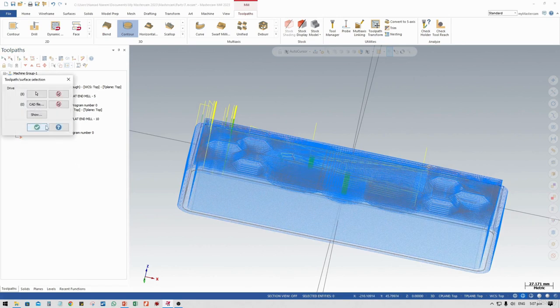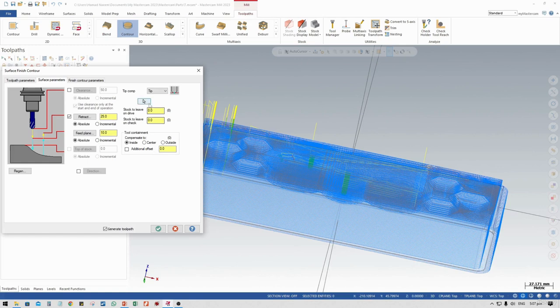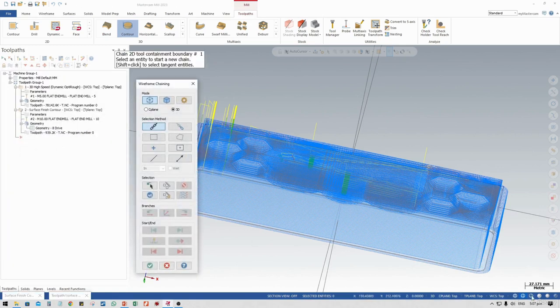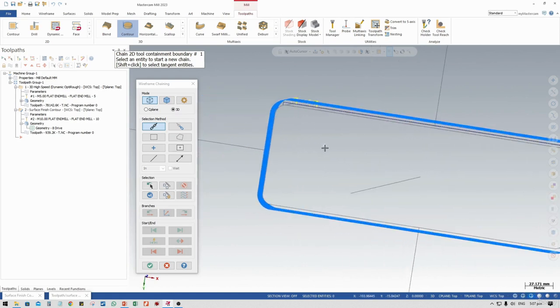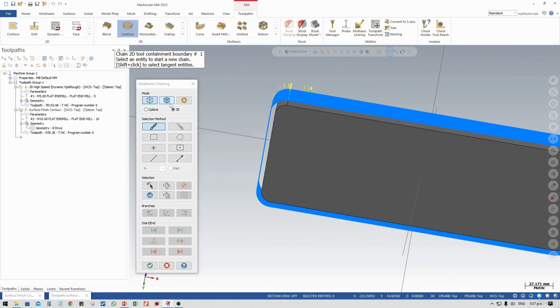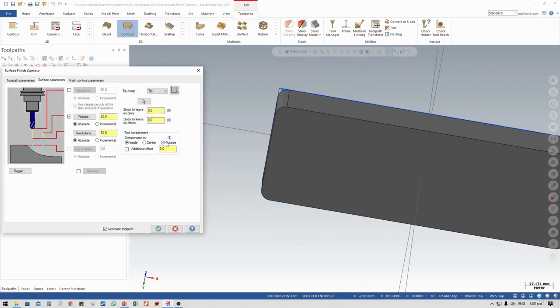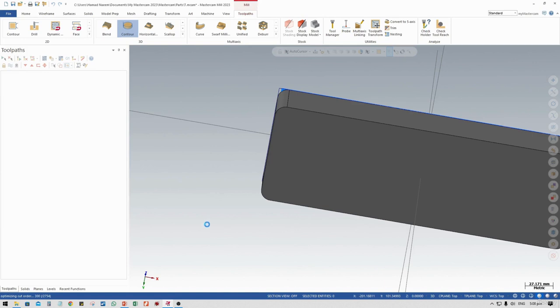Select twice. Go to parameters, toolpath parameters, and select the containment. Here, we need to select the containment. For 3D, let me show you. We want 3D, so go to 3Ds and select the surface. And inside, no, we do want it outside. So we're just creating and optimizing the cut order. It's taking the optimized cut order.